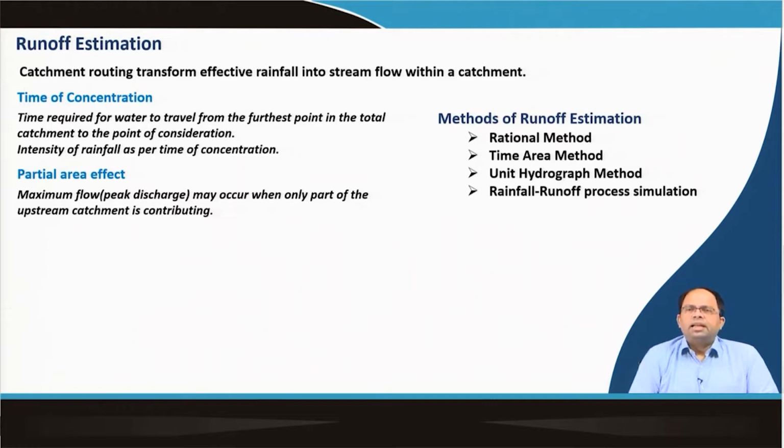But if this inlet is within a particular pipeline, the water that comes from the upper sections of the pipeline also comes from certain other catchments. So, we also need to consider that. That means the water that comes to a particular point reaches it not only from the surrounding land, but also from much farther away, via the pipeline, where that water has entered at some other inlet.